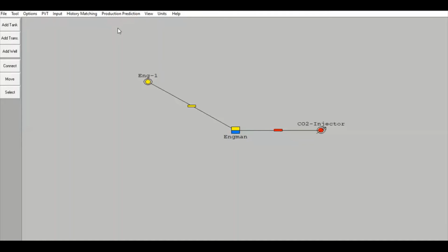First, we continue production until the end of 2024. We use this well model, and from the start of 2025, we convert the reservoir into CO2 storage, and we convert the well to be a CO2 injection well. We provide the TPC, we provide the injectivity, and then we continue with the CO2 injection prediction step.